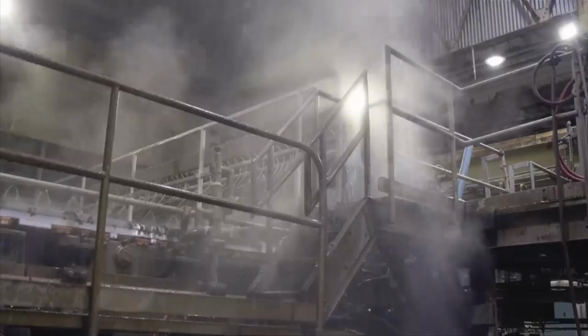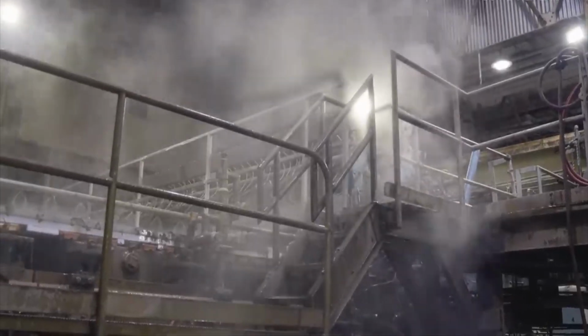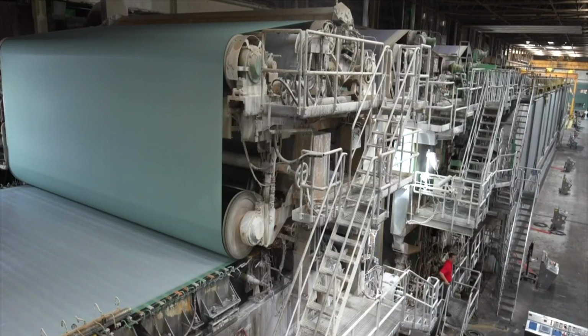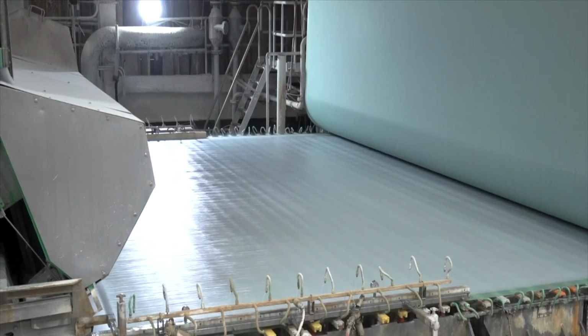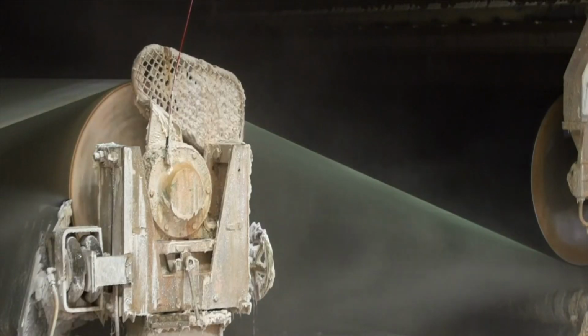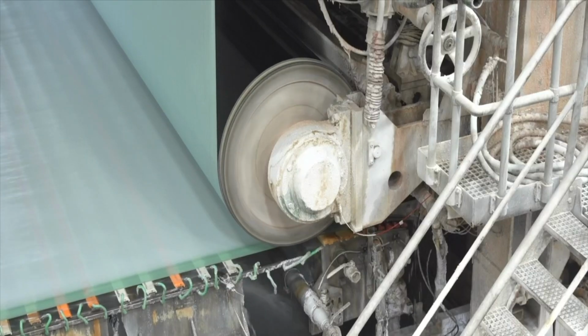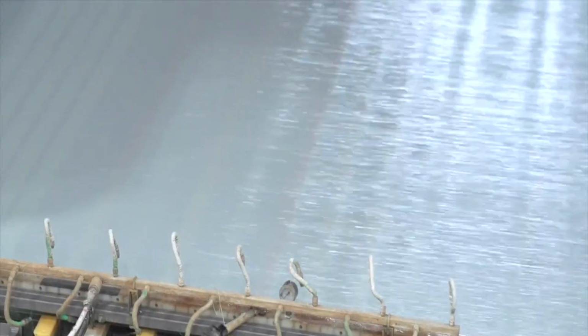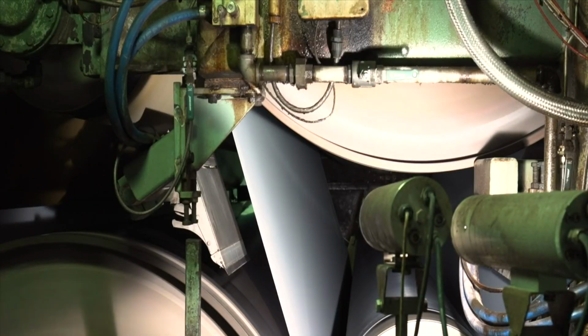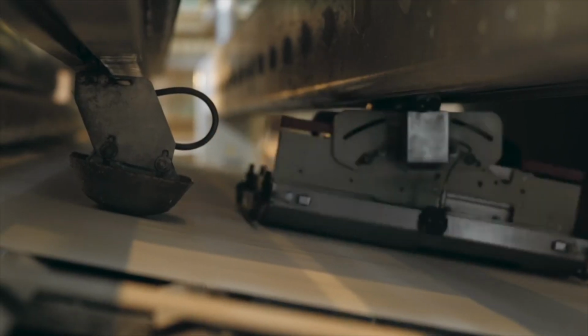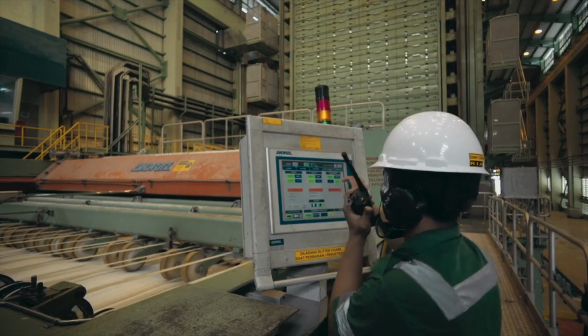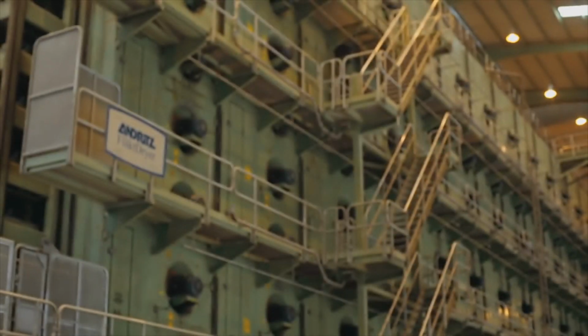Eventually, it builds up into a thin, wet mat of overlapping pulp fibers that become the paper itself after it's pressed and dried. The paper web next enters the pressing stage, where the objective is to remove even more water from the newly formed wet paper sheet. This increases the paper's density and mechanical strength while reducing overall bulk. Pressing is accomplished by passing the damp paper web through a series of heavy rollers that squeeze out excess moisture. Older paper machines utilize a whole series of press rolls that apply substantial pressure to the paper sheet as it passes through. More modern machines may instead use extended nip presses, incorporating a lubricated felt that transfers force over a longer area for enhanced water removal. The gradual pressure applied across the paper web during the pressing stage removes water to prepare the paper for the final drying stage.